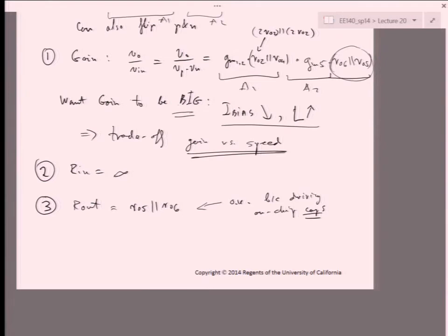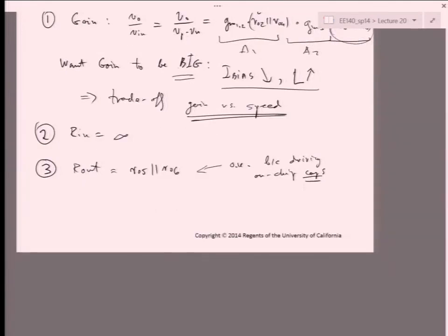So typically at the output stage there's some buffer, like a source follower or emitter follower, that would give you better output impedance. It replicates gain, but with much smaller impedance, so you can attach a big capacitor at the output and not make that a super dominant pole. Okay.